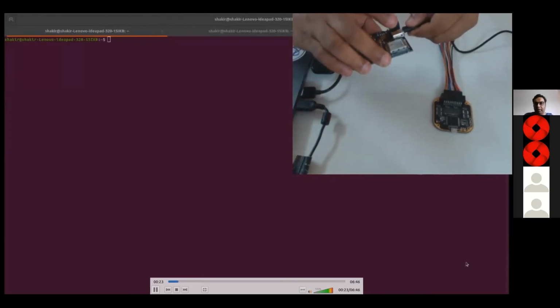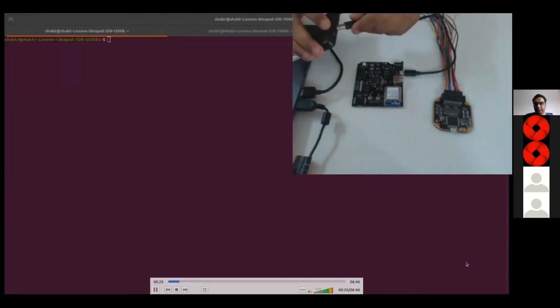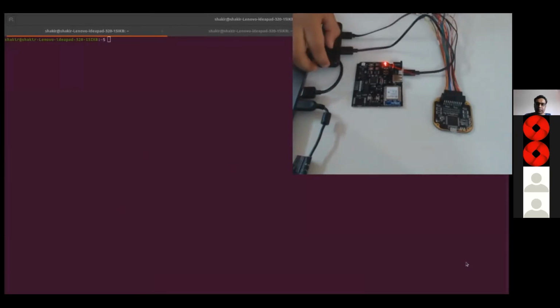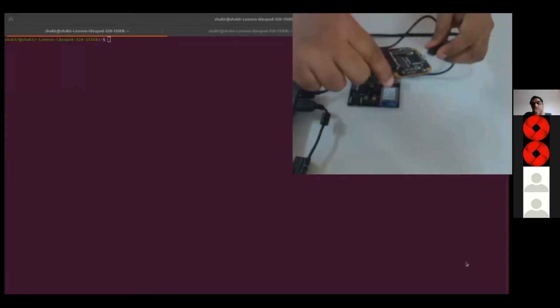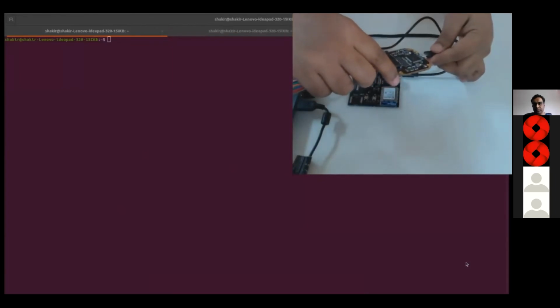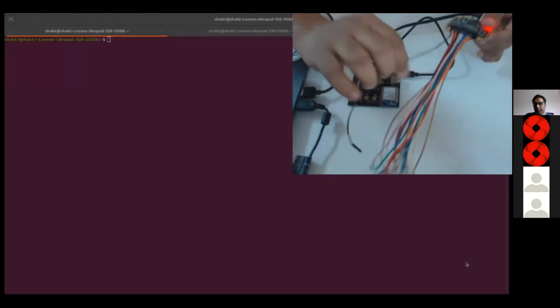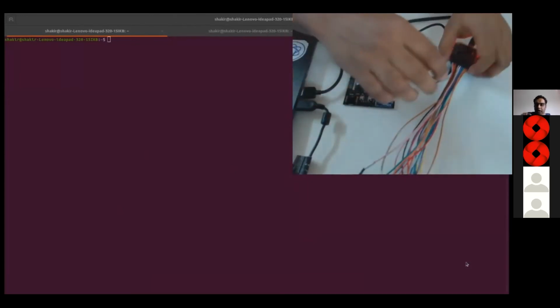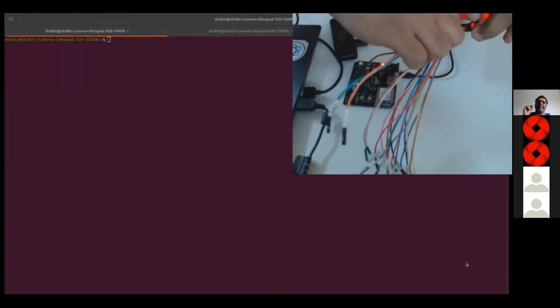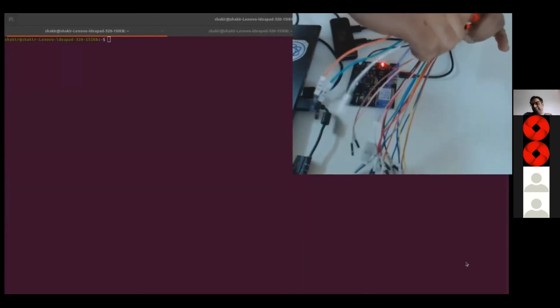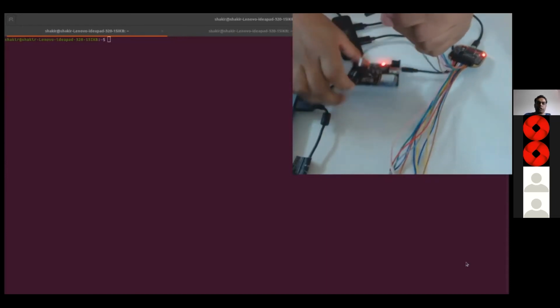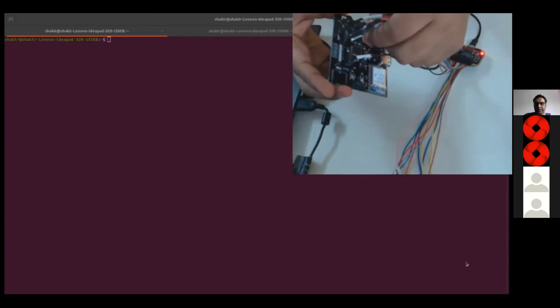Right, so let's power up this Diva board, and power the Bus Auditor. Now, one thing that you need as a common is the ground pin. We have demonstrated how we identify the ground pin in our previous webinars. So if you go to our EXPLIoT webinars, you will see the UART to shell webinar where we demonstrated how to find the ground pins.